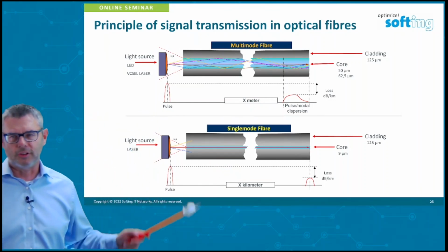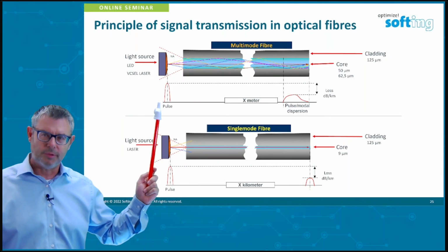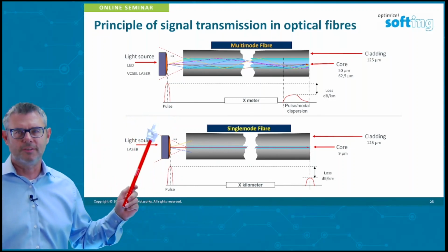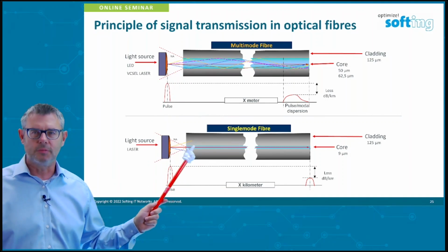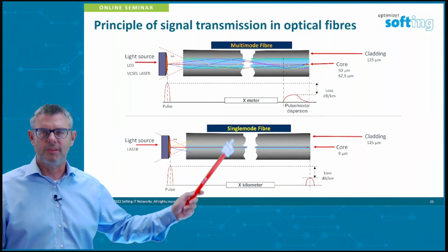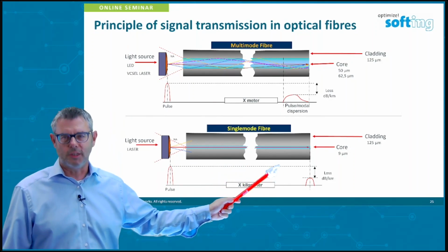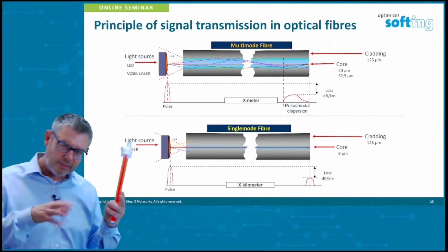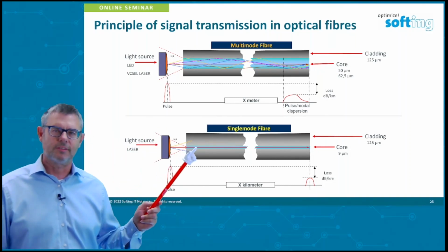So there are certain limitations on multimode for long distances and also for too high frequencies, high protocols, high speeds. If you want to go long distances, you cannot allow multiple modes. You just use one single mode, one beam of light, to go through the small core. This allows us, without modal dispersion, to go a long distance. We have certain attenuation that lowers the amplitude, but the pulse itself stays pretty sharp. There is chromatic dispersion, but this would lead too far today. But this is the way to go long distances: single mode fiber.